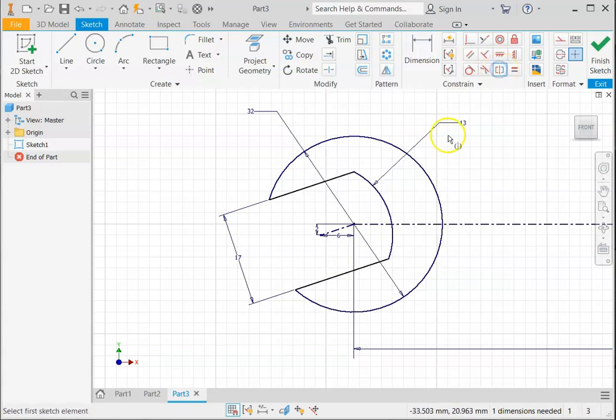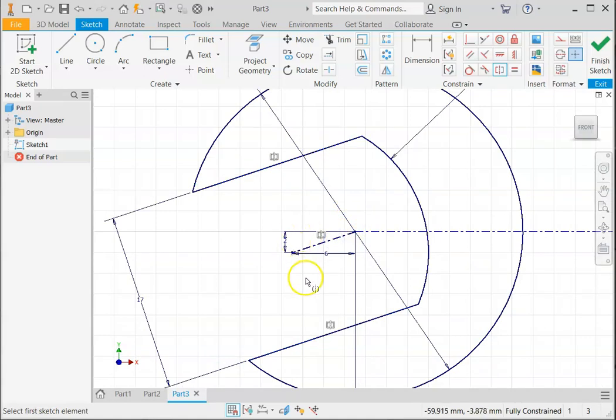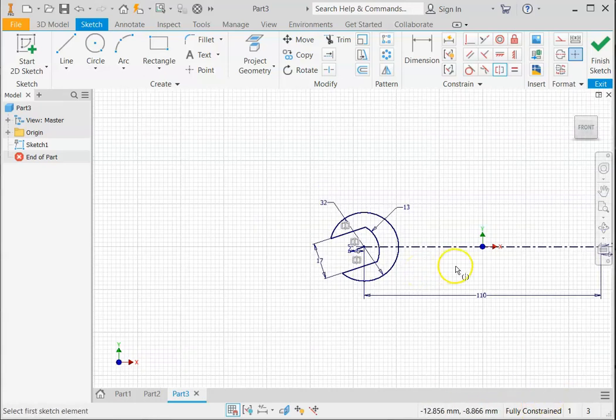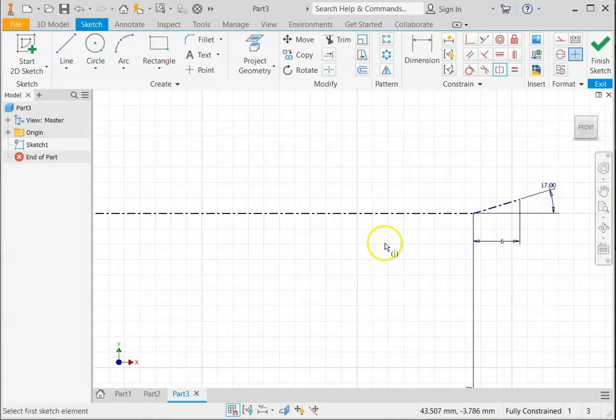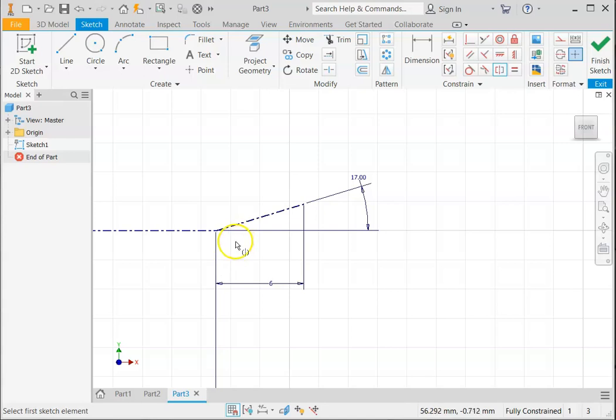By selecting this, you pick the outside lines first. These two lines are going to be symmetrical with each other in reference to this middle line. Now that adds those constraint symbols, and you notice they're all fully constrained. We will repeat these on the left side. So I'm going to repeat the whole thing again on this side. This makes the video a little bit longer, but I'm going to do that right now.